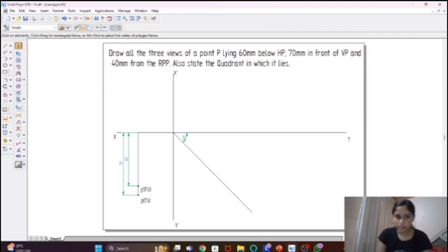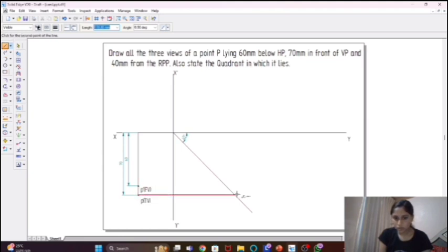Reset. Then again you can draw the line here. Extend the top view to the 45 degree line. If you cross the line, it shows 90 degrees or straight line, but when you move to the 45 degree line, you can see that the 45 degree line turns red, so that is the correct position. Click here, then extend the line 90 degrees above.